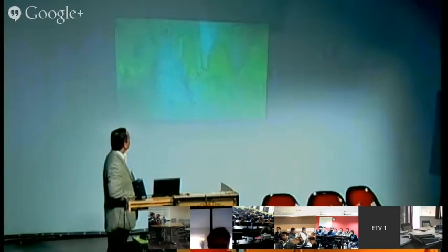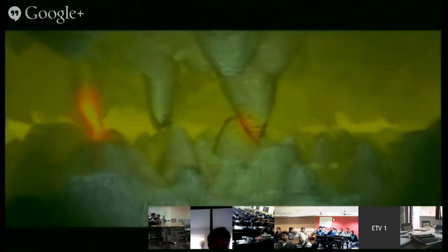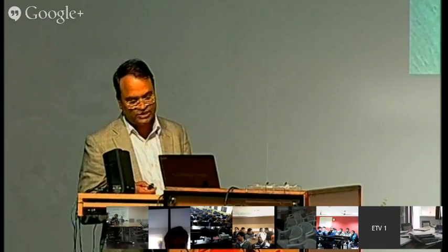So depending on the surface topography of the piston ring and cylinder liner, friction may be more or less. If sufficient film thickness is there, then surfaces will be separated, gliding is very smooth and friction is very less. Normally in the engine, thin lubricants are used so that power loss should be less inside. The viscosity of engine oil is very low.